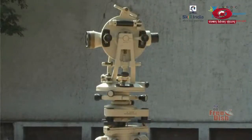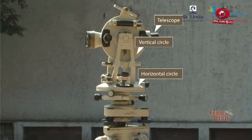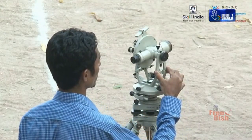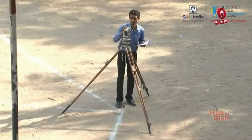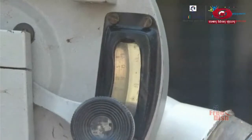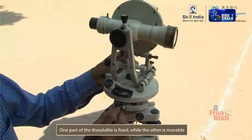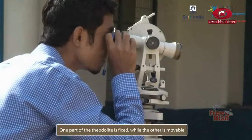Let's first take a look at the theodolite. The theodolite is a combination of devices like the telescope, vertical and horizontal circles, vernier frame, among others. The theodolite can measure horizontal and vertical angles accurately. As a device of indirect measurement, it is typically used to measure the angle of elevation of an object at a known distance so that the object's height can be calculated. It is possible to take such measurements with the theodolite because, while a part of the instrument can be fixed, the other part can be moved in different directions.